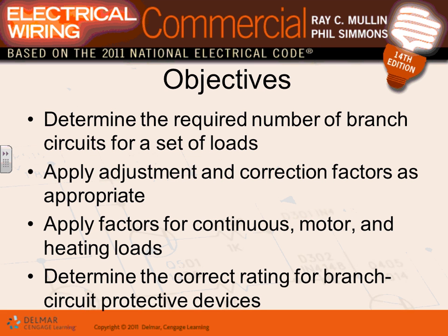If your wiring method is conduit, or if your wiring method is MC cable, which it will be in a commercial building, it will be very beneficial for you to use 3-phase cables, meaning you can carry 3 circuits with a neutral in one cable. You can't carry more than that, but the typical, if you're using cables, is at least 3-phase cables. So you can carry 3 circuits, 20 amp circuits, and a common neutral with MC cable.